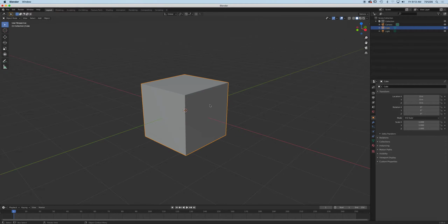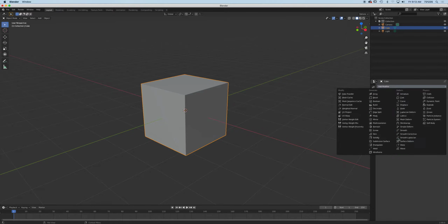You can get them right here on this tab where it looks like a wrench. And you're adding this in object mode. You don't add them in edit mode. Okay. If you go to that wrench right there, you see this add modifier panel. I am in drop down, and everything that can be applied to that object will be here. It's quite obvious in Blender. It's like object-oriented programming. If it's not something you can use, it'll be grayed out.